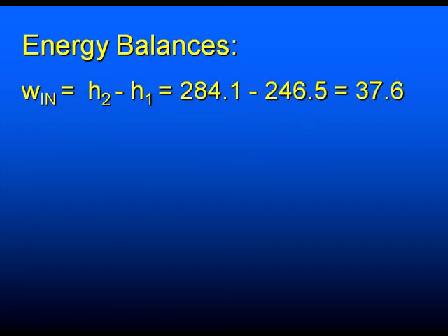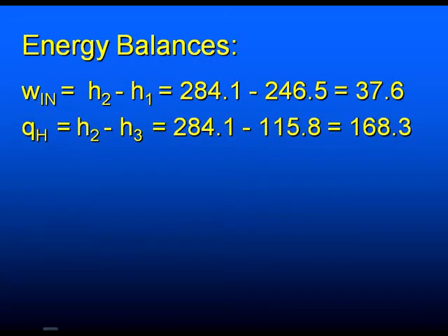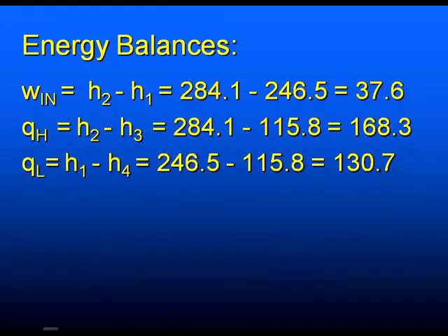Now, if we do our energy balance, the work in is 37.6. The QH rejected to the surroundings is 168. QL is 130.7, and notice the work plus QL equals QH.